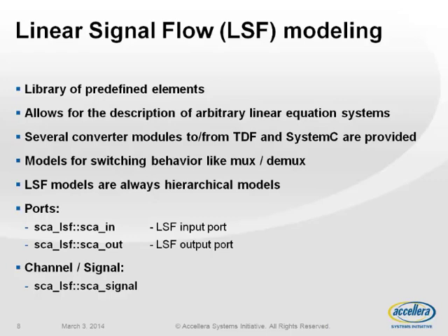If you want to define an LSF port, you will have to use this kind of construct, SCA LSF SCA in. If you want to have an output, same thing, SCA out. And in order to connect the different primitives together to perform the function or the model you want, you will use what is called SCA signal to connect different primitives together.